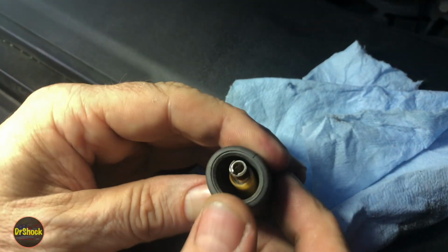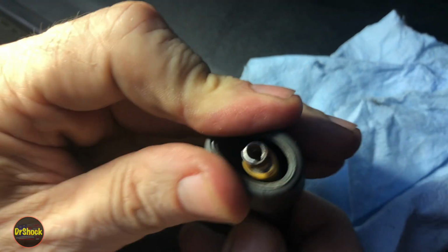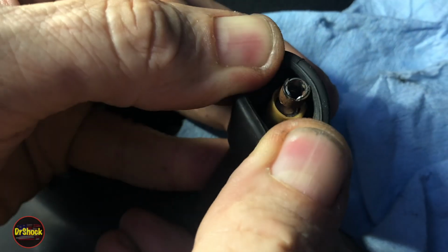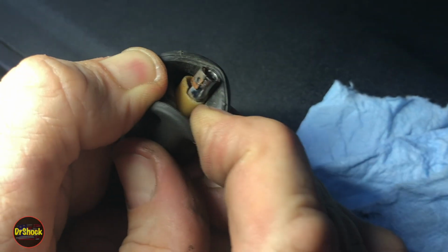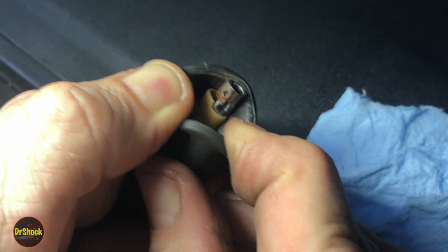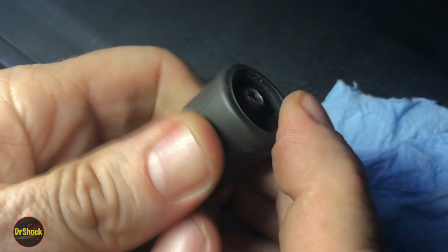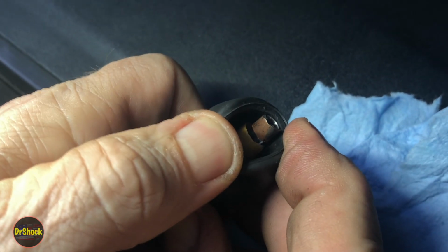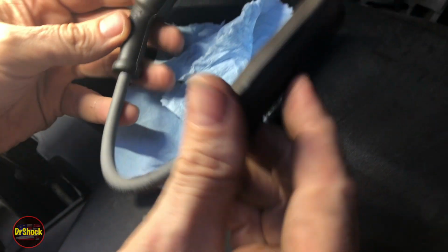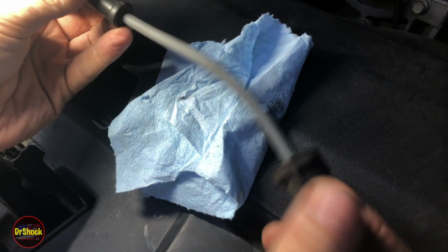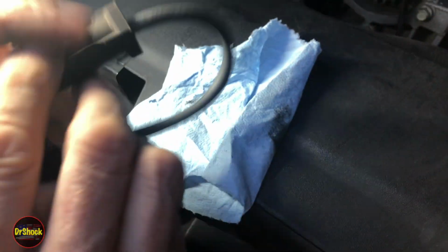And one other thing I wanted to show you, a lot of these old boots are burned on the insulator. You see it's all brown. In fact, go on this side here. If I pull the boot back, you can see it's cracking and coming apart. And it's also got corrosion. That's rust. So these are not GM parts. These are some kind of aftermarket thing. That's why they're out of spec, and that's why their quality is pretty poor. So good garbage to remove from the engine.